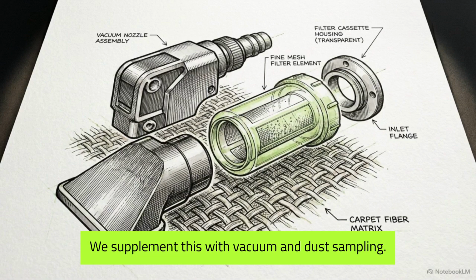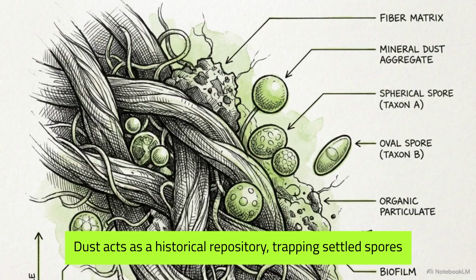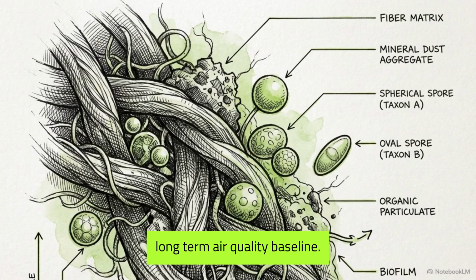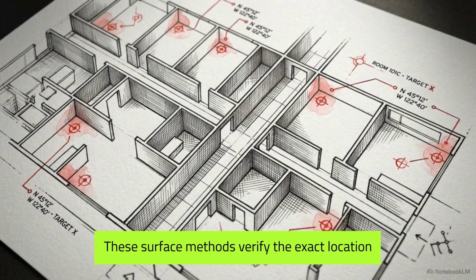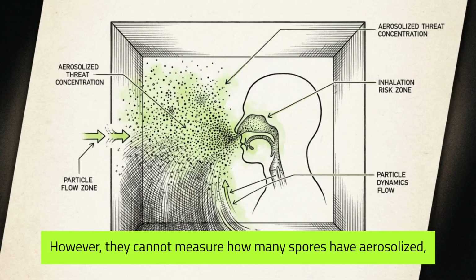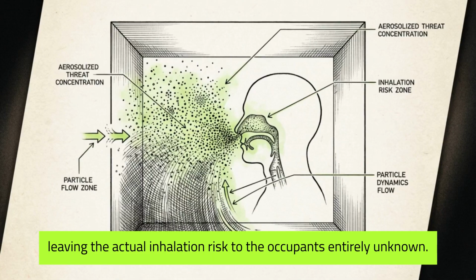We supplement this with vacuum and dust sampling. Dust acts as a historical repository, trapping settled spores over long periods to reveal a building's long-term air quality baseline. These surface methods verify the exact location and physical footprint of a colony. However, they cannot measure how many spores have aerosolized, leaving the actual inhalation risk to the occupants entirely unknown.